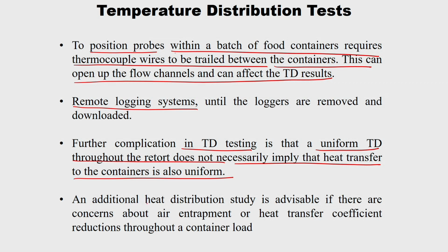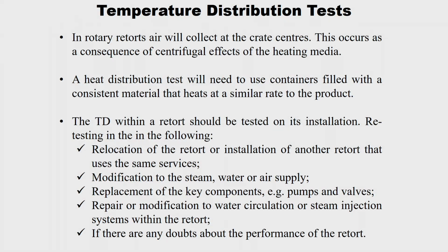Then an additional heat distribution study is advisable if there are concerns about the air entrapment or heat transfer coefficient reductions throughout the container load. So, this is what we have discussed. And in rotary retorts, air will collect at the crate center. This occurs as a consequence of centrifugal effects of heating media.